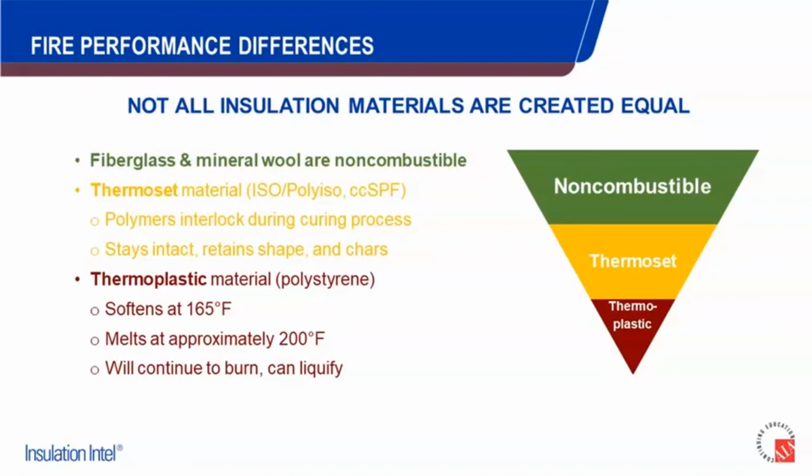There's tons of testing out there with metal panels and mineral wool CI insulation behind that, so just things to be aware of there. Eliminating one trigger point is not necessarily your silver bullet, but it can definitely be one option of taking that component out of play from compliance.